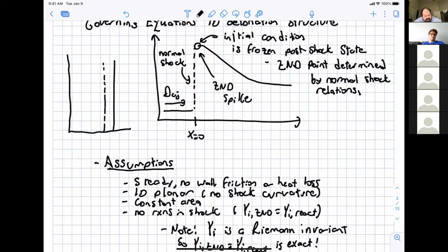So if there's a boundary layer that forms, it's only in this teensy little portion way down here. Okay, that makes sense. Basically, for most detonations, this is the portion that is affected by the boundary layer. Even though the reaction zone here is sonically isolated, the boundary layer starts from the shock itself. And so it's occurring inside of the detonation, and this boundary layer region does affect the detonation.